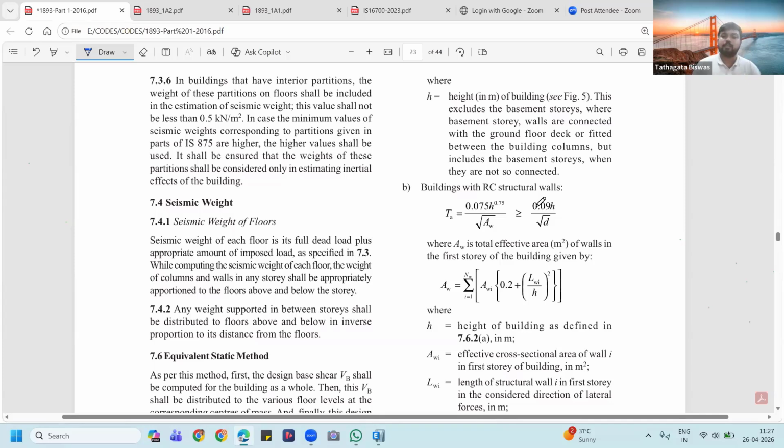In those places you have to go for shear wall structures, where the lateral load resisting capacity of those particular elements is quite a bit higher, because if the force is huge, the shear movement is huge, which is to be encountered. So if you have a bigger lever arm or bigger length, you can easily support the shear. So that's why the L is generally huge for shear walls in comparison with the D or the thickness. So that's why it is called shear walls, which is quite a bit different from a column.